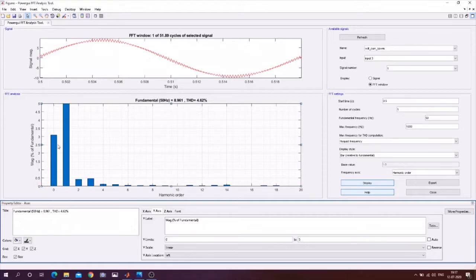Okay, so you see that some DC values are present, and the third harmonic and second harmonic are present but not so prominent. Okay, it constitutes less than 1% or less than 0.5% of the total waveform. Okay, and you could easily see that from this part. So we will just keep a note of this THD that is present in the waveform.